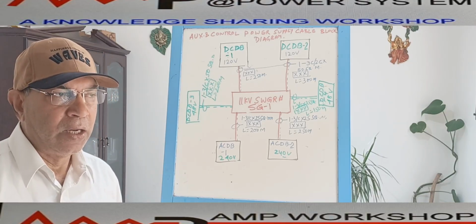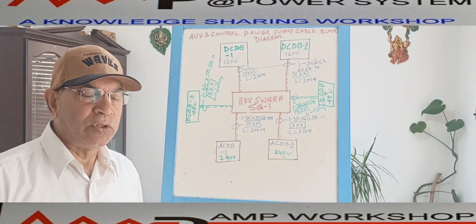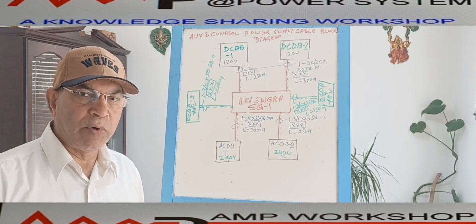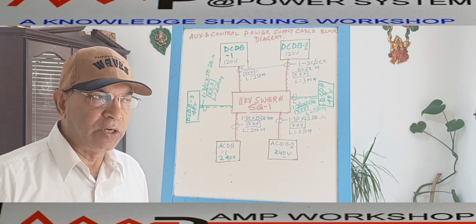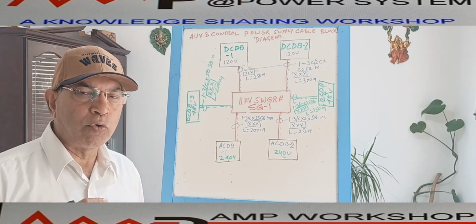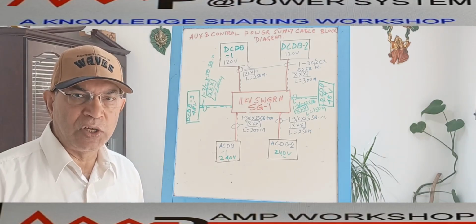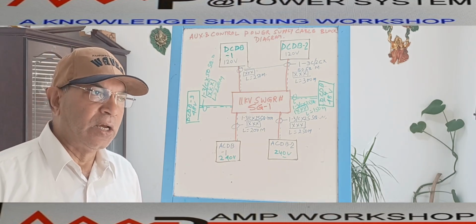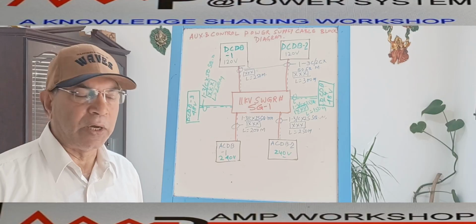That means from the control power supply point of view, we are considering that this 11 kV switchgear has two control supplies. One control supply is 120 volt DC, which will mainly be used for circuit breaker closing scheme, closing power, circuit breaker opening power or tripping power, and at the same time various auxiliary relays power supply, because all the auxiliaries have a coil which needs to be energized. That coil supply we are also considering under the 120 volt DC supply.